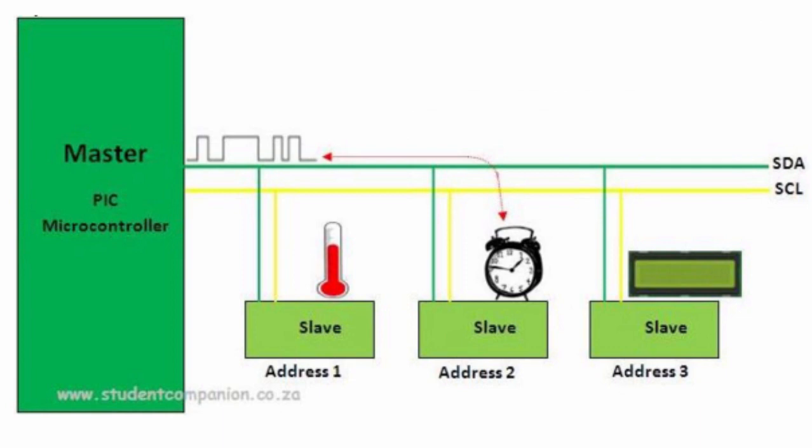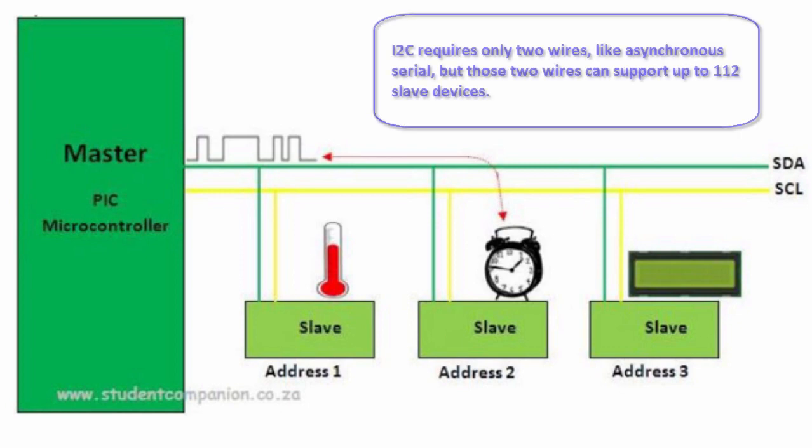Another advantage of using I2C over SPI, as we're going to learn in the SPI tutorial, is the number of pins used. Connecting a single master to a single slave with the SPI bus requires a minimum of 4 lines. Each additional slave is going to require 1 additional chip select input-output pin on the master.